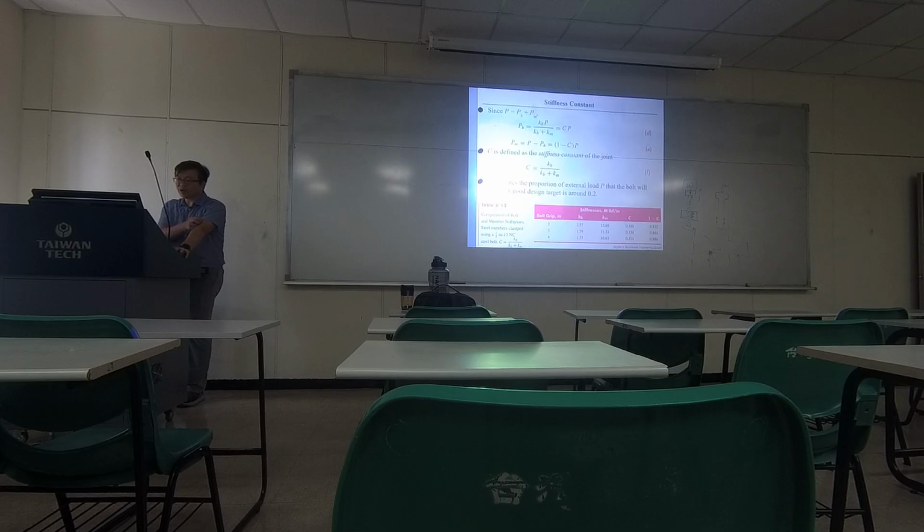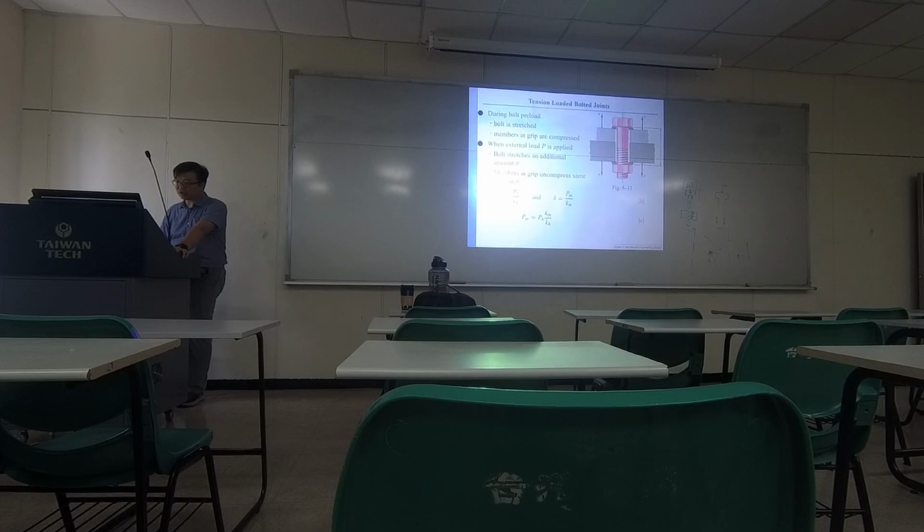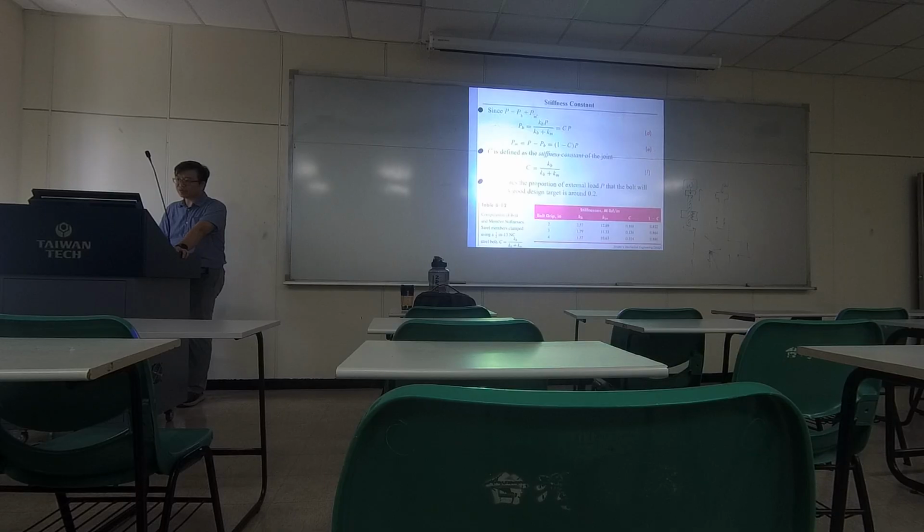So usually you will apply a certain force to have an initial grip. And right here, we are trying to use the equation. The total force equals the force inside the bolt plus the force inside the member. So you can then end up with the second equation.